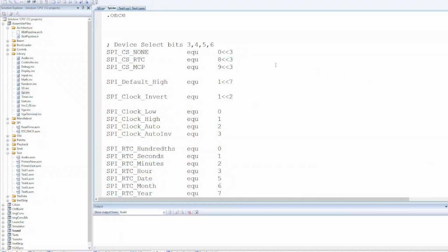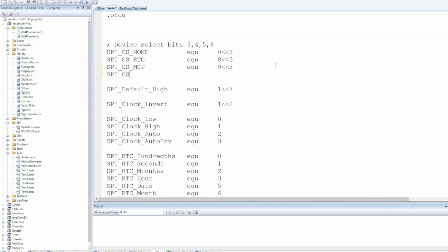Before we do anything else, define the chip select line. Now I've got the specifications for the SD card protocol, but unlike the other devices where we've got a fairly simple structure of set or read from a register, the SD card protocol is quite a bit more complicated.